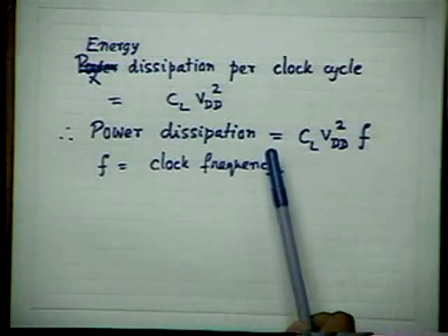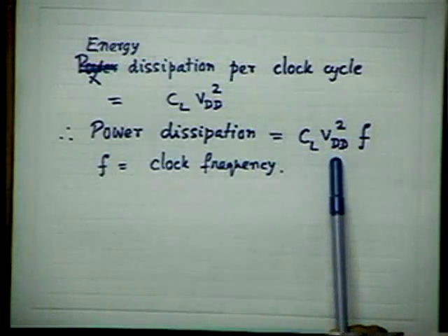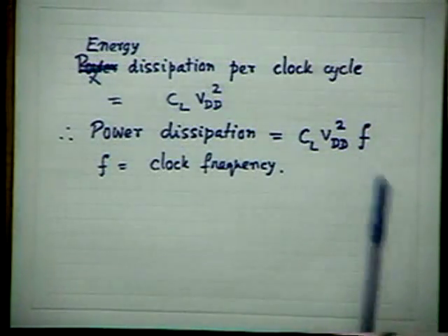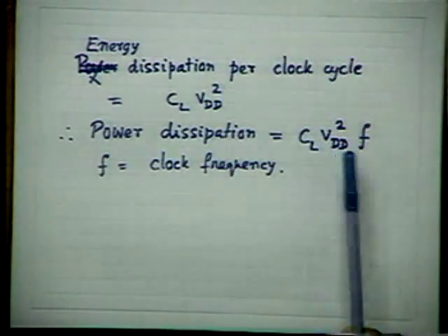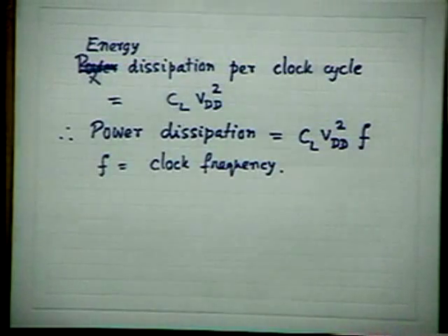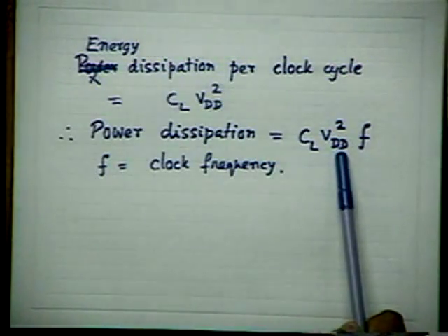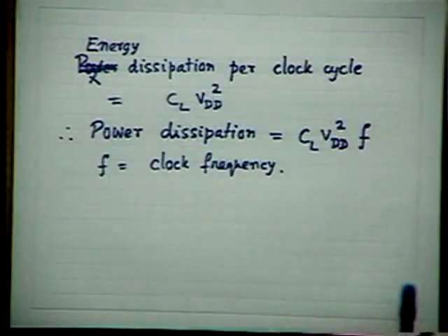So that's how the present generation CMOS has a tendency to have a power supply voltage which is lower and lower, but below 1 volt there is practical difficulty imposed by noise margins. So up to 1 volt or 1.1 volt is a limitation imposed by the various considerations today. And clock frequency, of course, nowadays the highest clock frequency which has been achieved is no limit, but at the commercial stage, as you know, several hundred megahertz. At the non-commercial research stage, gigabits.